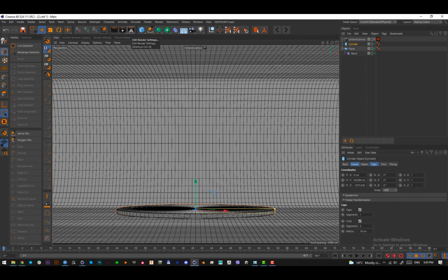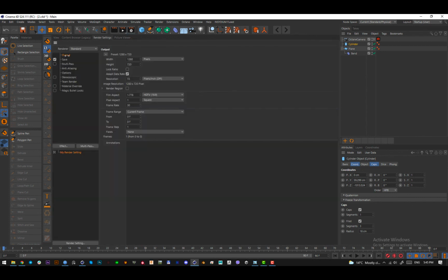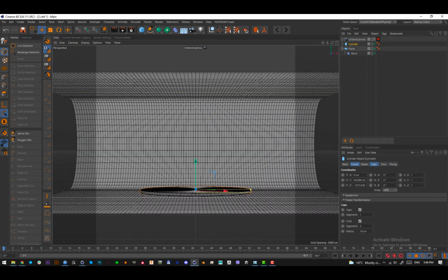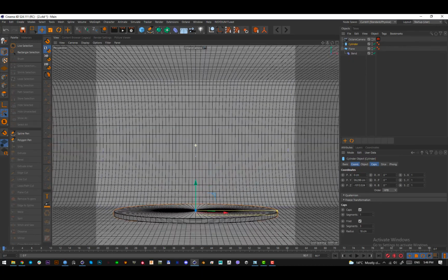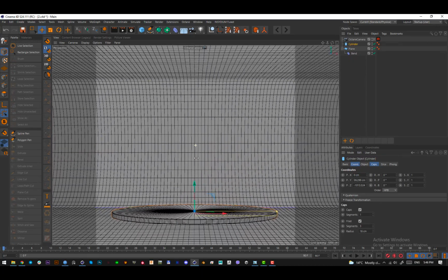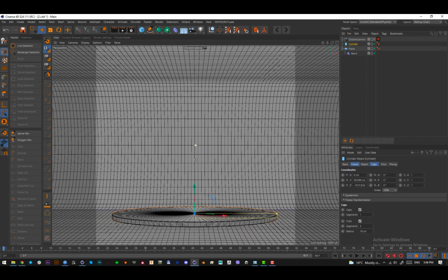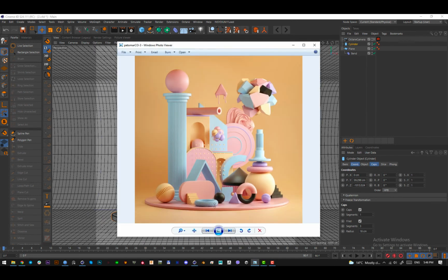Okay, let's begin with this. Jump to the render settings. On output, change the height and width. Actually set it to square. So you can just copy this value here and lock ratio, since we're going to be shooting from the square view. Now the camera is a bit changed, so you should zoom it out a bit like this. And just reposition the camera so that the cylinder is in the middle. Okay, this is it. Let's now actually decrease the height of the cylinder a bit more.